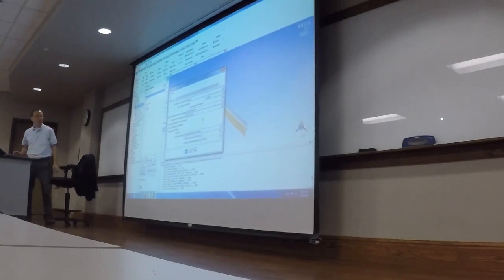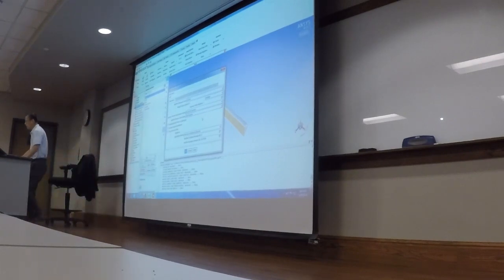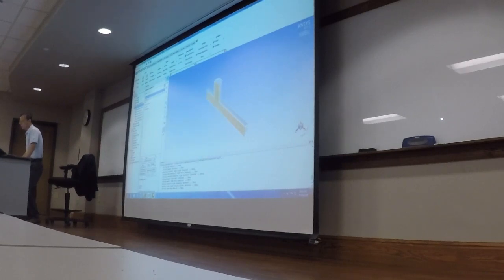When we specify turbulence, let's use intensity and hydraulic diameter. Intensity, let's give it 5%, and hydraulic diameter, this is a 2-inch pipe, so let's make it 2. Okay. Exit 2, exactly the same. Change the type to pressure outlet. Pressure outlet, 0 pressure. Intensity and hydraulic diameter, 5%, and still 2-inch.